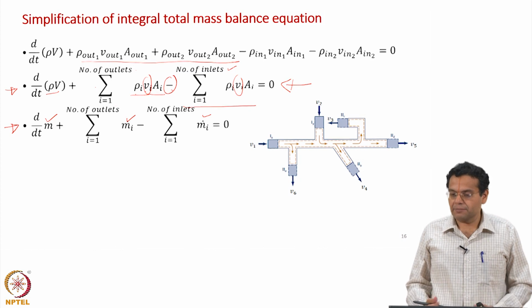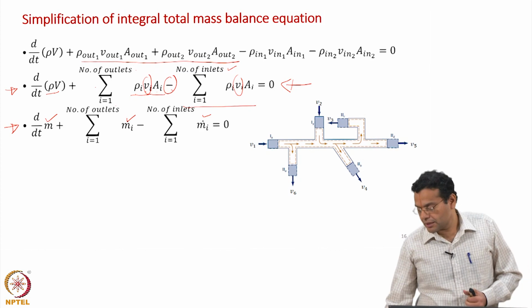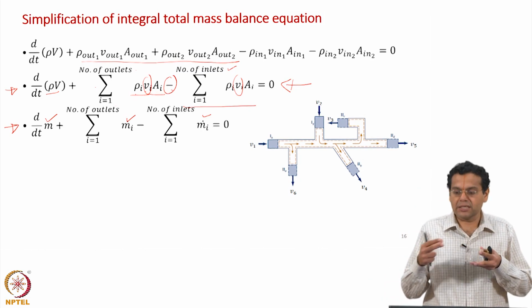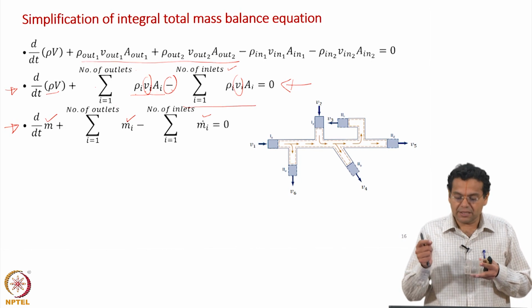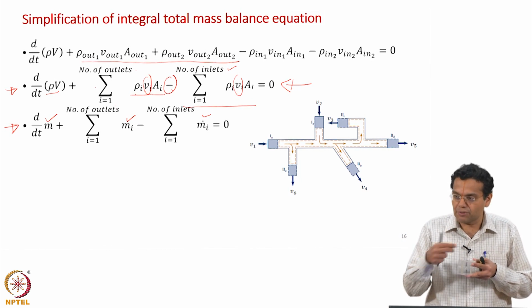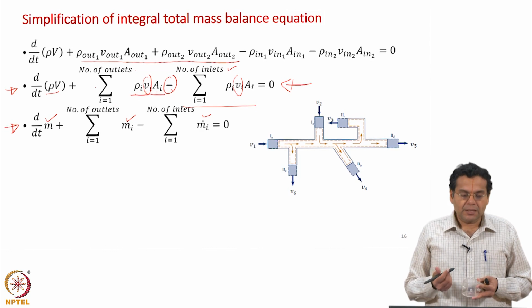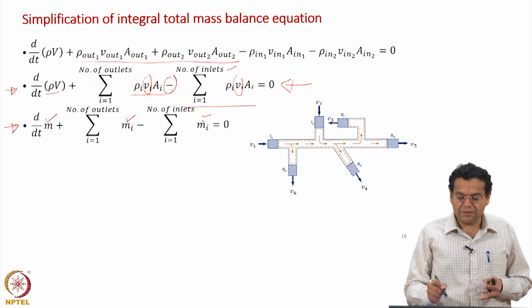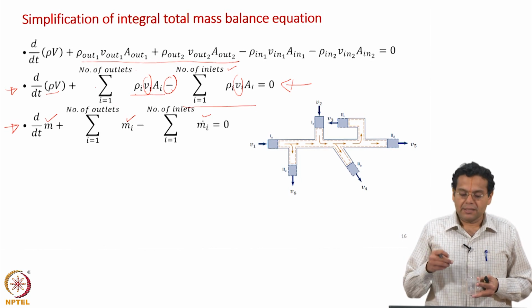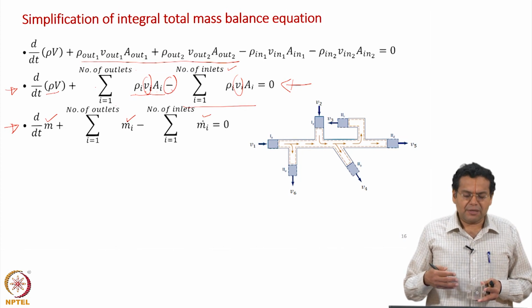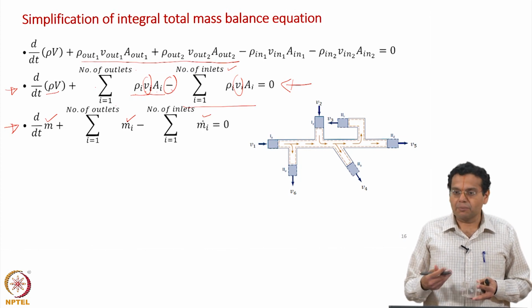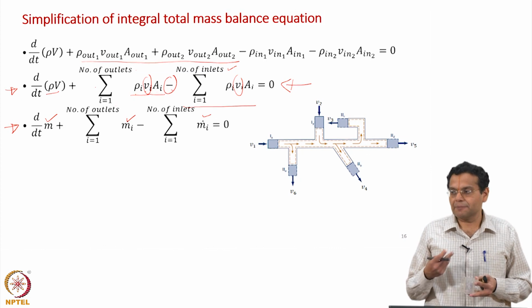Those are the measured variables. If you have a control volume with continuous flow in, flow out, usually you measure the velocity, area is known, density of the fluid stream is known, or you measure it. So, you represent in terms of rho I, V I, A I, but sometimes from a problem solving point of view, the mass flow rate may be given to you directly, okay?